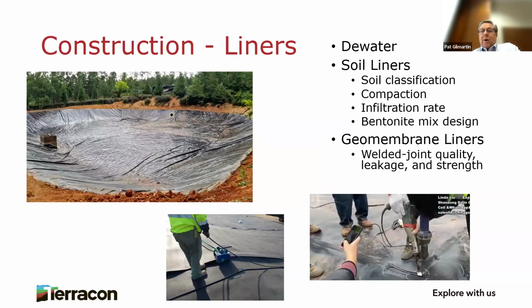Liner installation may require dewatering efforts to provide a relatively dry, stable subgrade for the liner, especially for excavations with groundwater seepage. Maybe we're excavating this pond in the wet winter with perched water table conditions in Durham, and for 2 weeks the water seeps in. Well, the contractor needs to be prepared to handle that. Normally, you're not going to be building so far below the apparent water table that dewatering for these is a big issue. If bentonite is mixed with the soil, we recommend maybe some laboratory permeability mix designs prior to construction. Bentonite's not cheap. How much does it take? Can't answer that question until I mix some bentonite with your soil and test it.